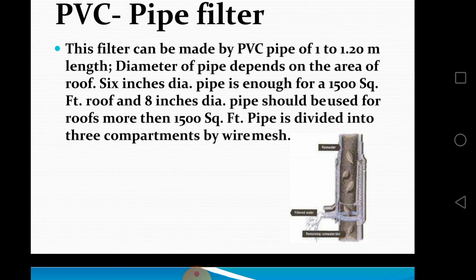We can go for tanks and simple tanks, and rooftop harvesting if it is an urban area, and radial wells, parking lot storage, and recreational park ponds. Various schemes we can develop in built up areas. In open areas we can go for percolation ponds and infiltration galleries, community wells, farm ponds, open wells, ducts, and aqueducts across the streams.